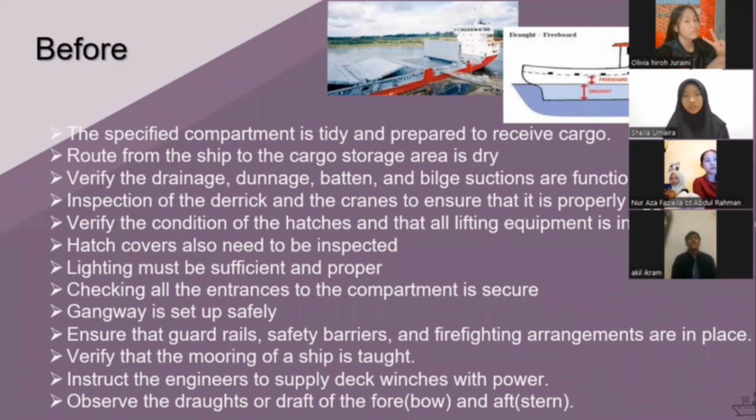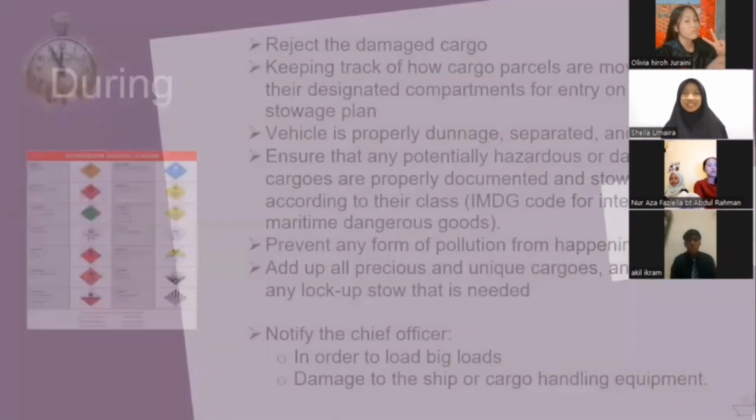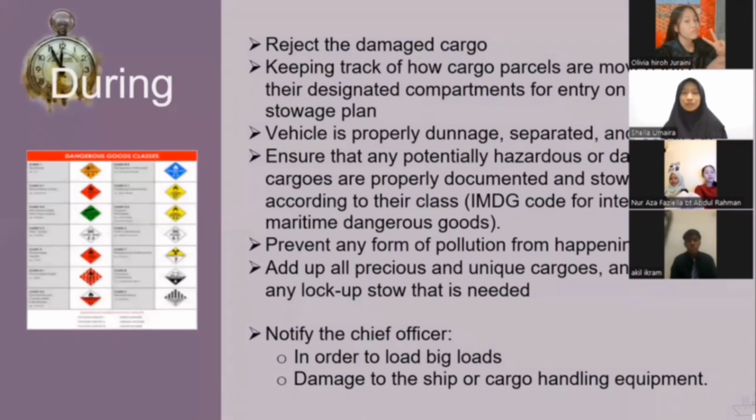And the mooring of the ship is started. Before cargo operations, we need to instruct the engineers to supply the deck winches with power, so everything will be functioning. The last duty before cargo operation is to observe the draughts, or draft, of the fore and aft. Draught is the British spelling and draft is the American. So you can see it in the picture.